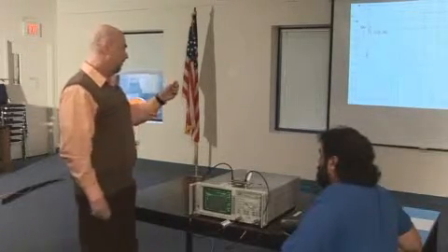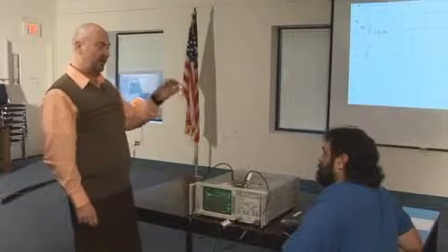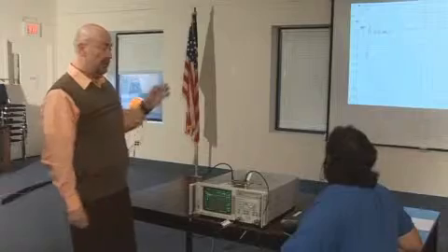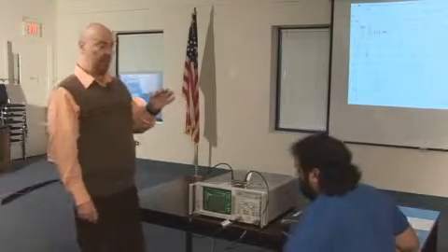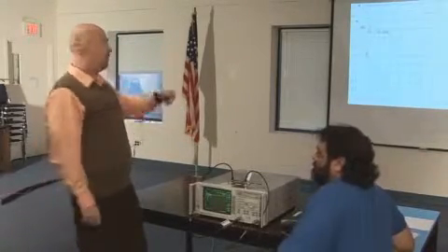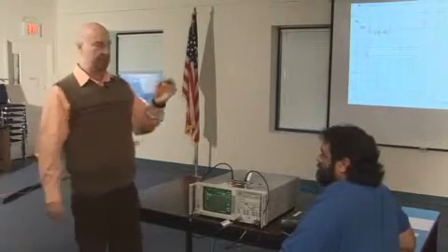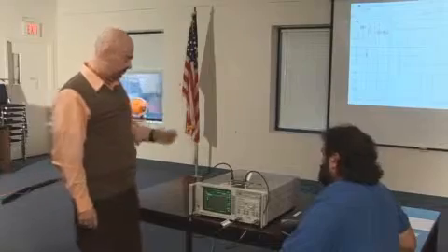So with just a single cap where you have a very well-defined point, as you can see by the slope of that, you may miss your signal entirely. And as you go up in frequency, if your problem's, say, not at 73, if it's at 200 meg or a gig, you may miss this by hundreds of megs.